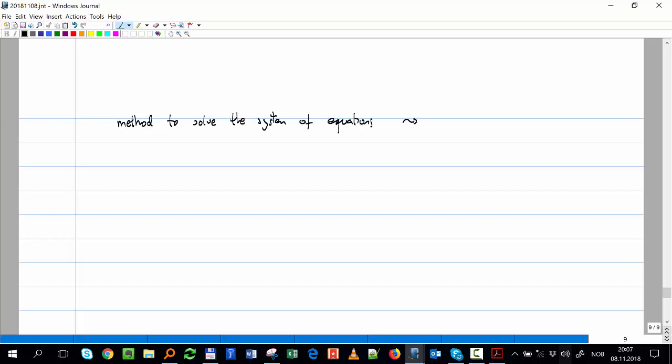And the goal is to avoid iterating with the composition xi or yi. I don't want to iterate because if I have 10 components, 30 components, it's just too challenging to choose all of them. So I just want to iterate just with FV, just with one. But for that I have to do some massaging.